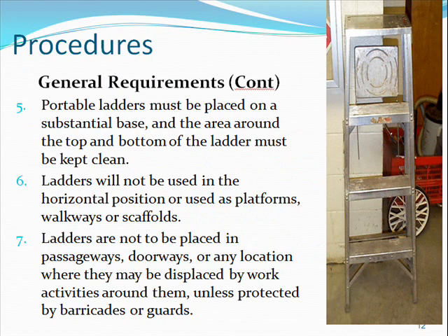Procedures, general requirements. Portable ladders must be placed on a substantial base, and the area around the top and bottom of the ladder must be kept clean. Ladders will not be in use in horizontal position or used as platforms, walkways, or scaffolds. Ladders are not to be placed in passageways, doorways, or any location where they may be displaced by work activities around them, unless protected or barricaded or guarded.